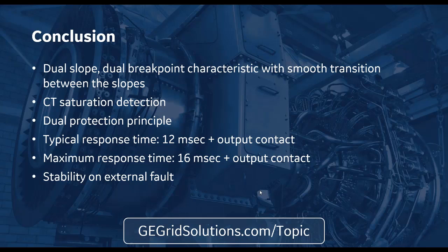And mostly what I see in North America for high impedance are legacy schemes. So upgrading a legacy high impedance scheme, they might not want to touch the CTs. But in other parts of the world, people are still specifying high impedance even for greenfield. I think they just don't know the difference. Yeah, it could be that, or they're just used to that. People are creatures of habit sometimes too.